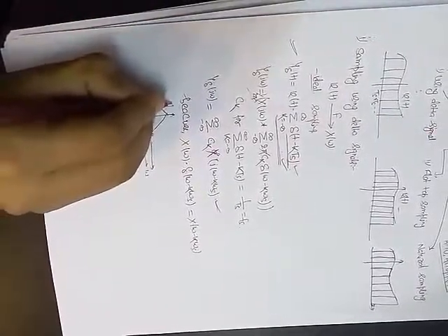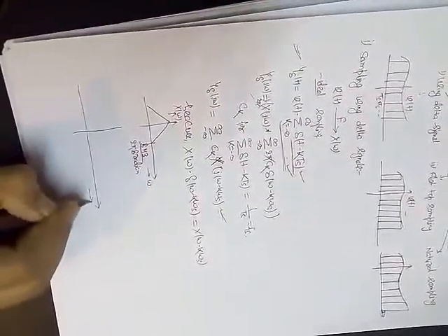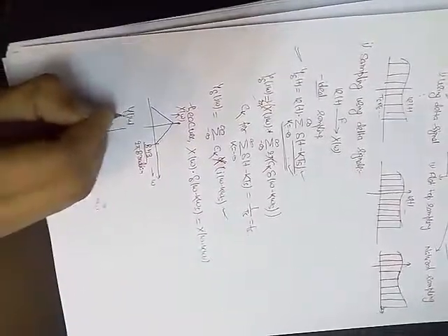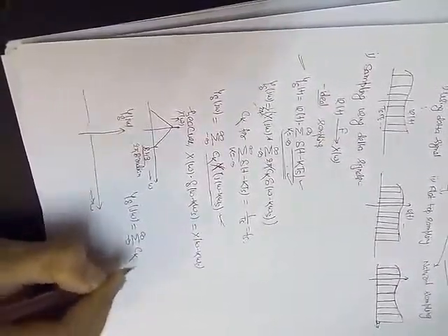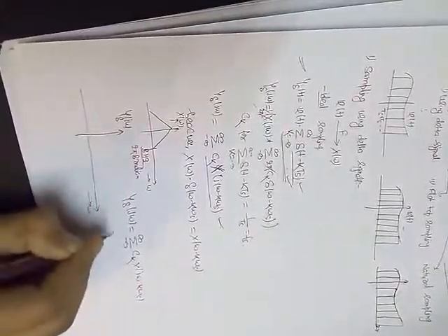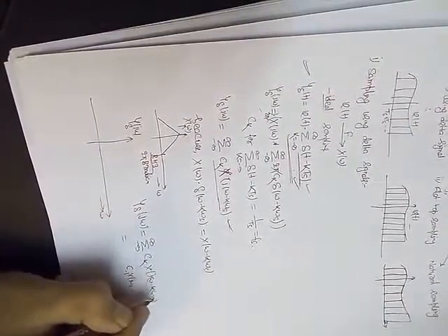So when we plot Y(jω) of the delta sampled signal, we expand Y_δ(jω), the summation of c_k X(j(ω − kωs)). Expanding, this is c0 X(jω) plus c_−1 X(j(ω + ωs)) plus c1 X(j(ω − ωs)).